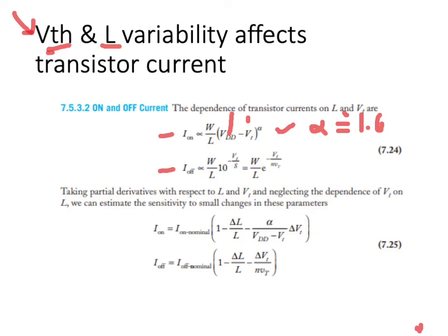And the off current, that is the non-conducting subthreshold current, has an exponential behavior because it's very similar to a bipolar junction transistor structure, where the actual value of the current depends on the threshold voltage here, and n is nothing else but a capacitive divider between the gate and the channel, as explained in previous lectures, and this value is roughly about 1.5 to 2 in modern devices. And VT is the Boltzmann thermal voltage, approximately 26 millivolts.